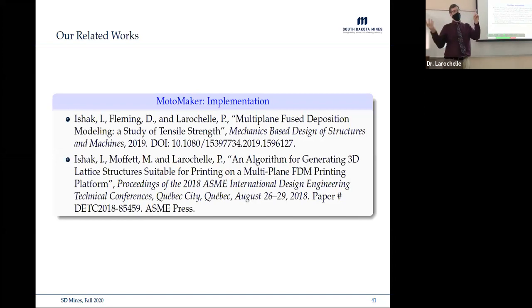It's nuts, but people are doing that. If you make the dog bone like this and start pulling it in tension, you're shearing all those print layers against each other, which is the weakest direction for the part. So we're able to extrude in any direction you want. The big advantage, we think, is being able to plan the printing process to yield the mechanical properties of the part that you want and need.